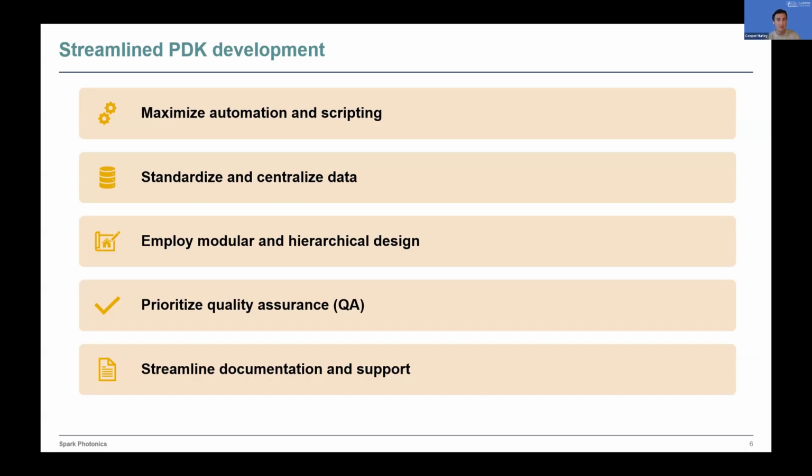Maintain updated design manuals and incorporate examples of different layouts inside your PDK. This can help users feel more comfortable designing into your platform with something they can compare as a good design. And then also get all your design knowledge and best practices into a really easy searchable database. This would also include maybe common issues that designers run into. That way you can reference this as sort of an FAQ troubleshooting guide.